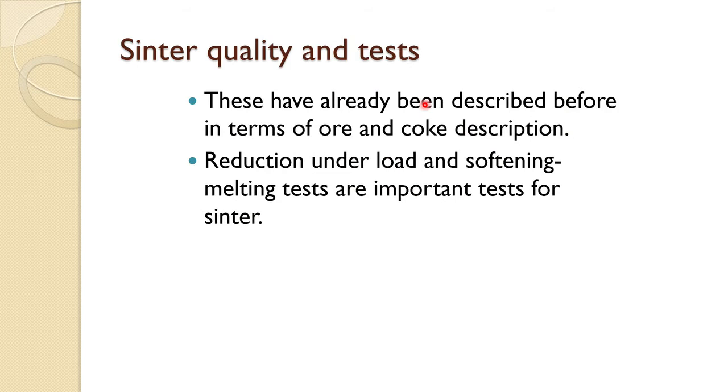Now we will come to the sinter quality and test. These we already discussed during the iron ore and coke description, so I'm not going to repeat them, but some important ones are that reduction under load and softening melting tests are routinely carried out to check sinter quality.